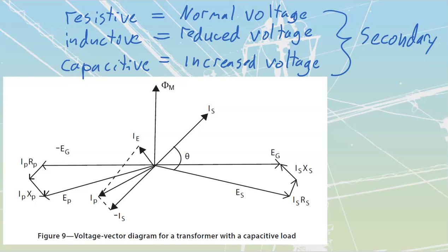So this is the reason we do not want to overcorrect our power factor. If we overcorrect and go capacitive, we lift the transformer voltage. As soon as we lift the transformer voltage, we run into problems where we burn out the transformer, we burn out equipment that's attached to it, ours, our neighbors, etc., and then we end up having to pay the bill for it. This is also the reason that we power factor correct, because otherwise we end up with too little voltage. We can end up with brownouts and things like that if we have too lagging of a power factor.